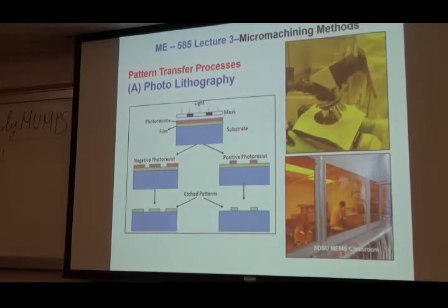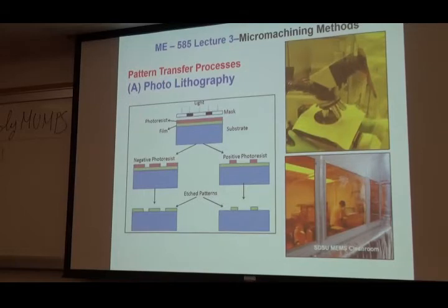Like I said, you have to do one complete litho process, which is deposit the photoresist, put your mask, expose it, do your thing. Then after you've done either addition or subtraction, then remove it. That's one litho process. You want to do the next layer, redo the whole thing. So that's why this is for patient people.